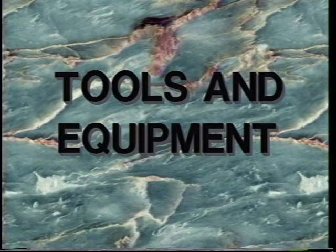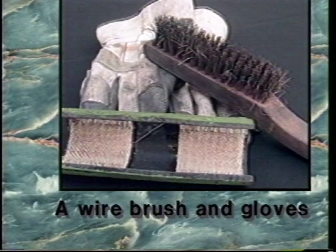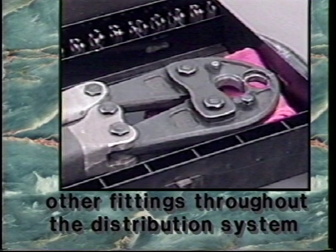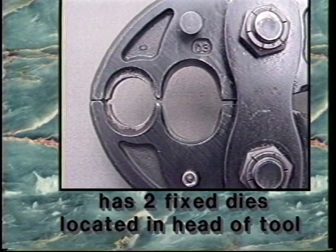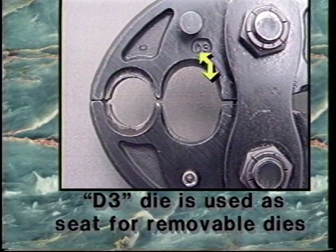Tools and equipment. The tools used in this video are a manual compression tool, a wire brush and gloves. The hand-operated compression tool is used to install connectors, sleeves, and other fittings throughout the distribution system. The compression tool used in this program has two fixed dies, which are located in the head of the tool. The dies are used to install different sizes of connectors. The dies are labeled O and D3. The D3 die is also used as a seat for removable dies.